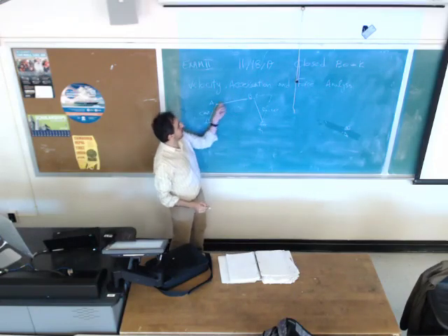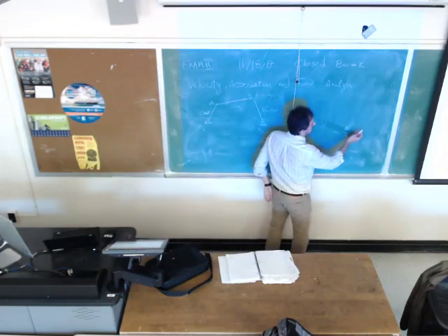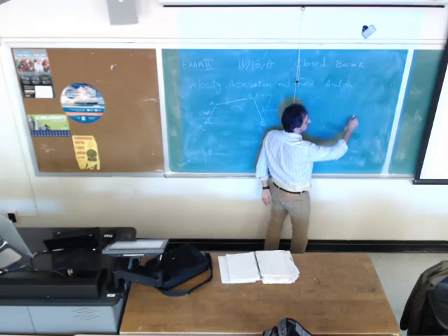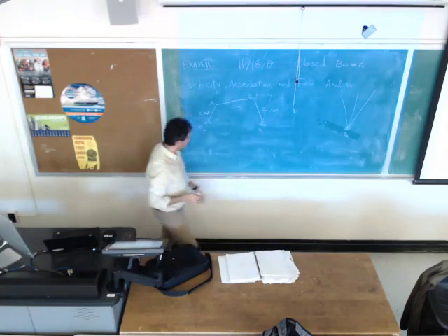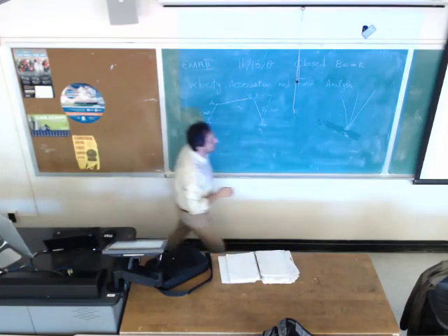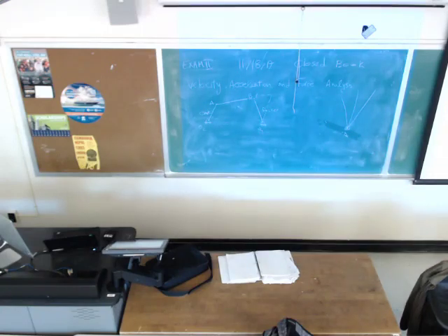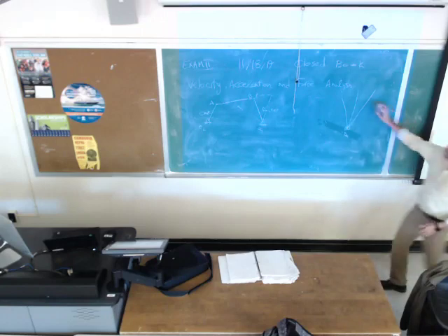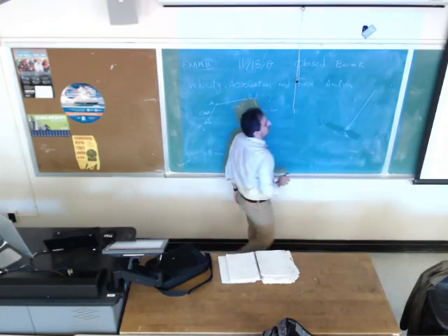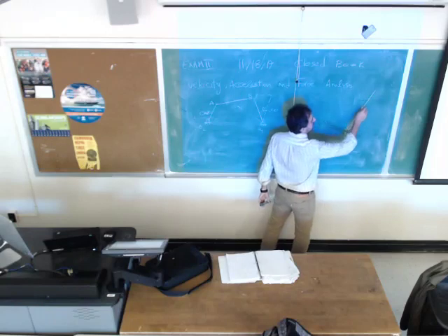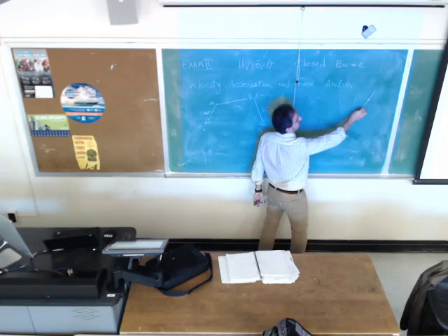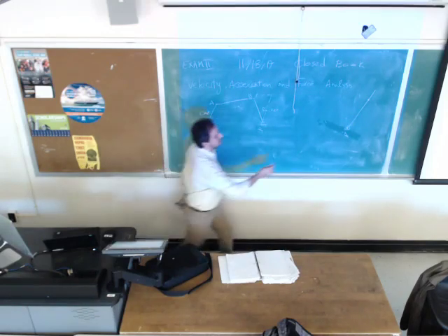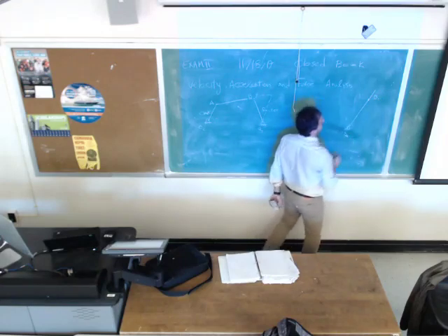I have to locate points B, A, and O2. Draw a line, just draw a desired line. It can be in any direction. It can be this line, this line, this line. So it's up to you. You can pick any line. I pick this one. On that line, just pick a point. I pick this point. You can pick any other point on this line. And label this as B1.